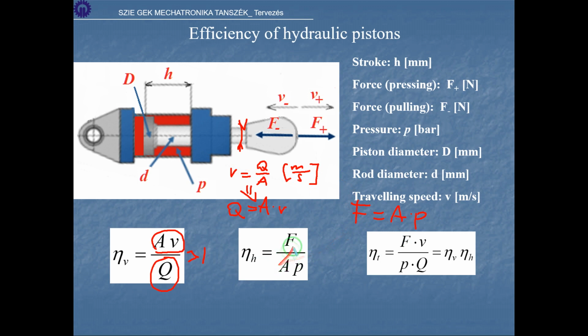So if I can measure the force which the actuator is providing us, it will be a smaller number than the theoretical number, because there are frictions here and here and so on. Therefore I have to provide a bit more energy to overcome these frictions. But this energy will be converted to heat, because friction is converted to heat, and the overall efficiency is easily calculable with this equation here.